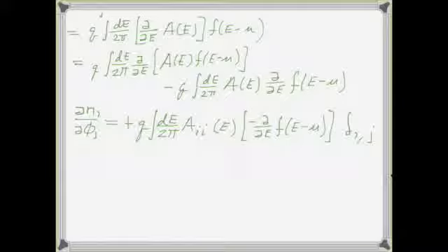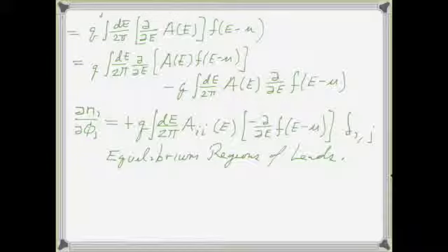Okay, so one approximation is that at a given site, you're approximating this derivative as diagonal, so you're not worried about dn_i/dφ_j. And all you're doing, from this perspective we talked about earlier, is that instead of shifting the potential, you're shifting the Fermi level locally, because we're talking about the equilibrium regions of the leads. So this is for the equilibrium regions of the leads. This would be the form of the Jacobian used in the equilibrium regions.